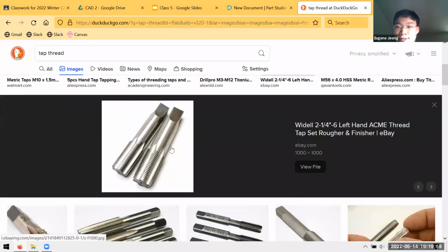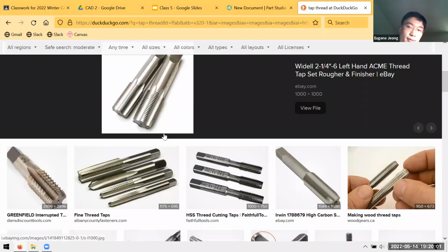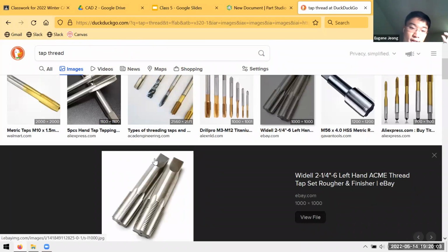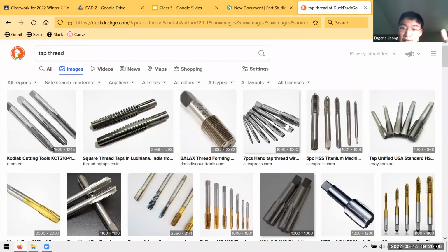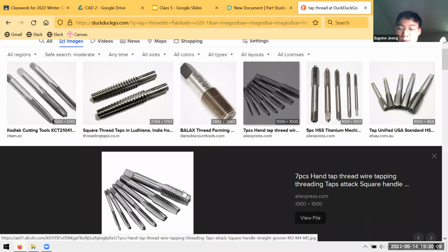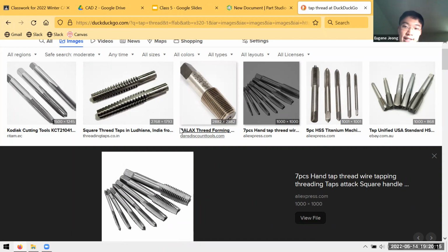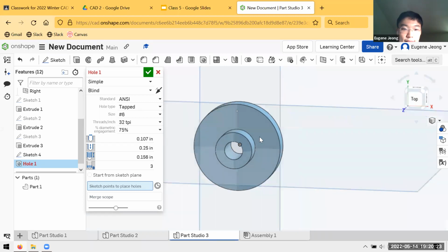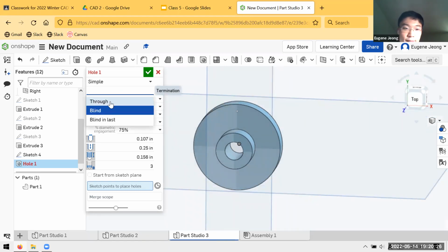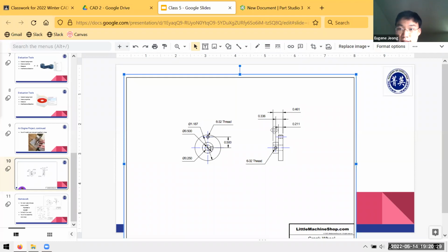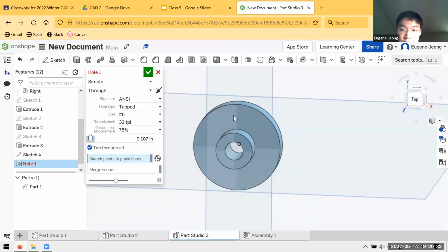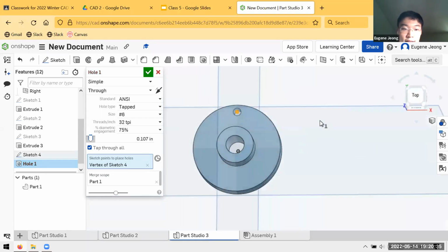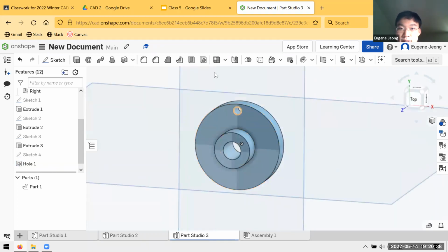So basically the idea is you drill a small hole, a hole that's smaller than your actual screw diameter. Then you just screw one of these in, and these little sharp points will cut the threads out. And then you pull it back out, and then your piece of metal has the threads in, so that a screw or a bolt can go in easily. All we have to worry about though, this is a through hole. It goes all the way through, as you can see in the side view. And the location is going to be here. And that's all there is to that one.